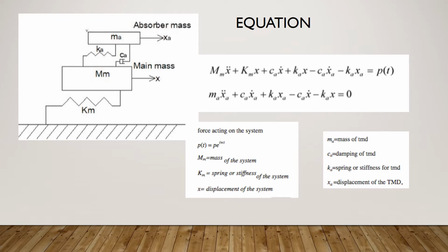Presently, the greatest concern is whether the TLD can produce a force large enough to counter the dynamic response of the structure. The largest theoretical force produced occurs when the frequency is set to 0.99 Hz. The maximum amplitude calculated for force is 191.406. It is important to note that the force is not symmetrical in direction. The case with the most symmetry is when the frequency is 1.01.